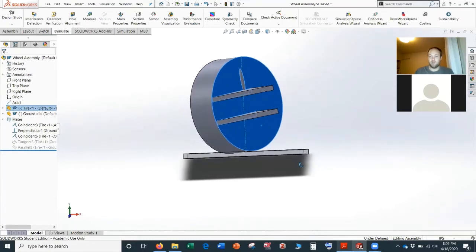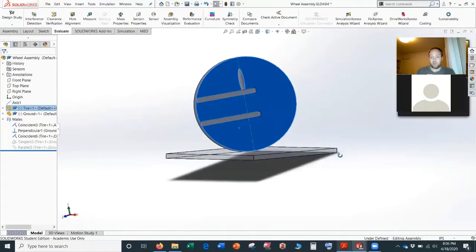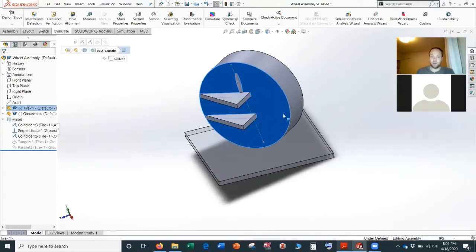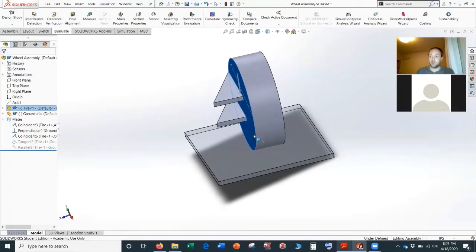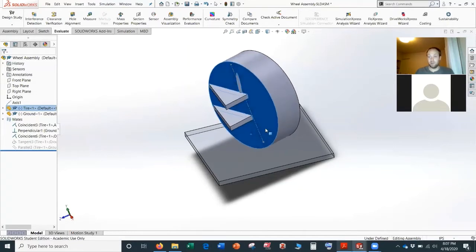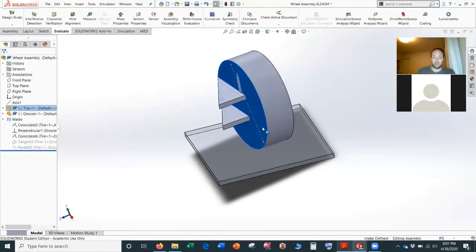So in both of these cases, your tire is basically pushing into the ground, and you basically have to lift your car up in the air slightly. So both of these are not going to be favorable, and what ends up happening is this provides some kind of self-centering of the wheel and some kind of straight line stability. So having some kingpin inclination is good for a little bit of that. For example, when you're driving and you let go of the steering wheel, the car is naturally going to return to straight, right? So having some kingpin can do that.